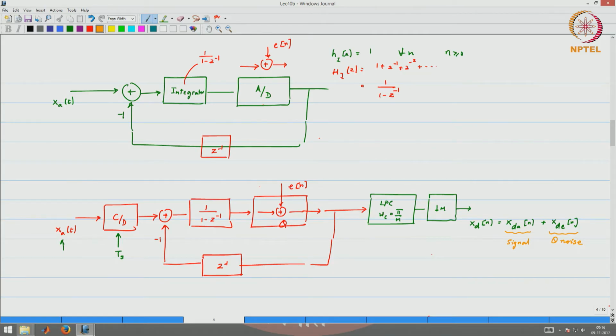So, now an A to D converter, is it an analog device, is it a digital device, or is it a mixed signal device? The input is an analog signal, the output is a discrete time signal. So, obviously, it has to be a mixed signal device. Okay. Now, where is the mixed signal boundary for us in this case? So, if you were to look at it as the input at this point where the analog is taken in, and then at the output the discrete time comes out.